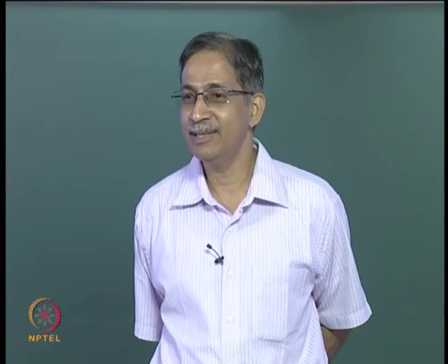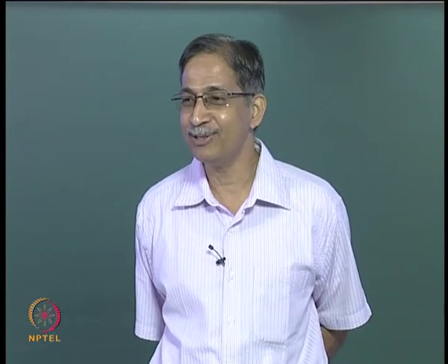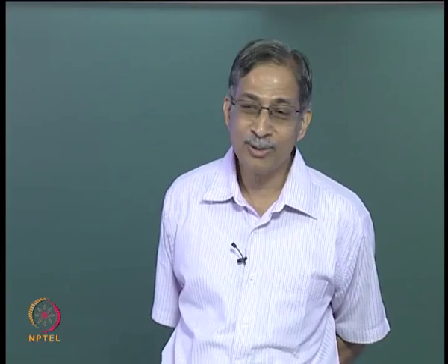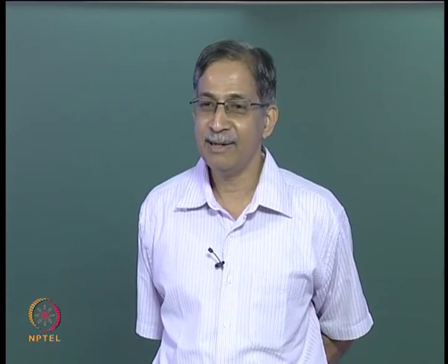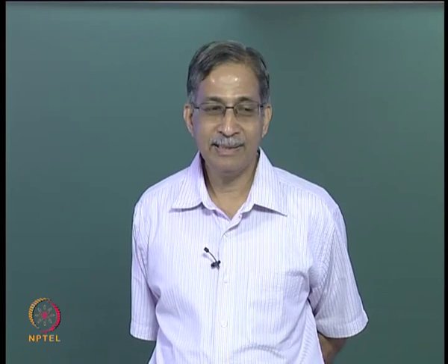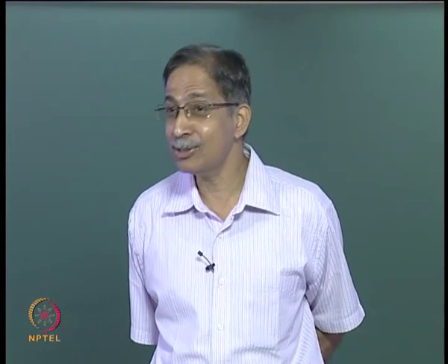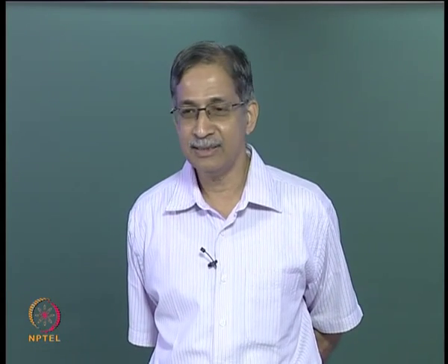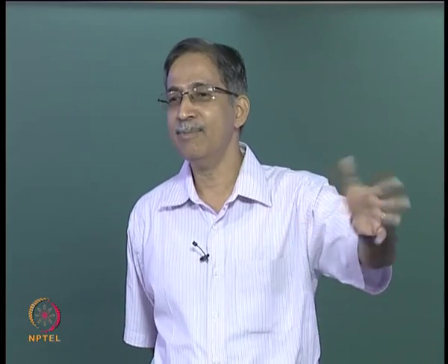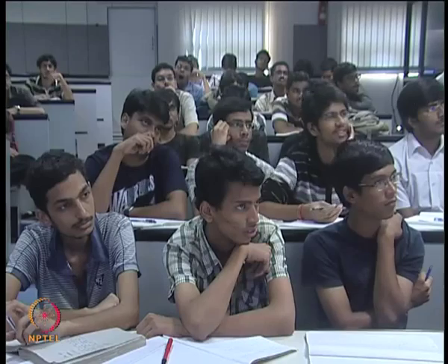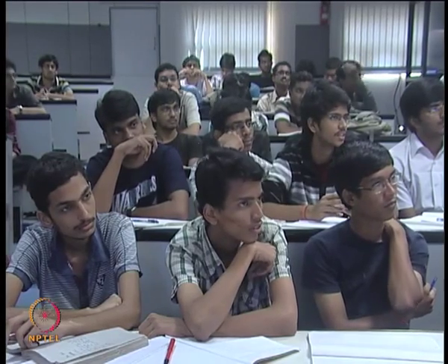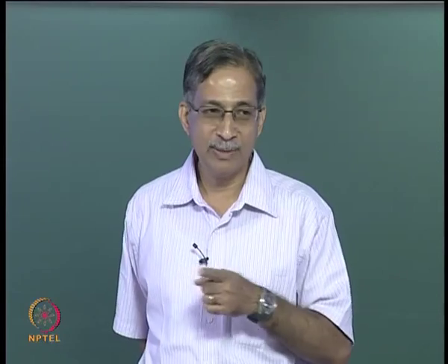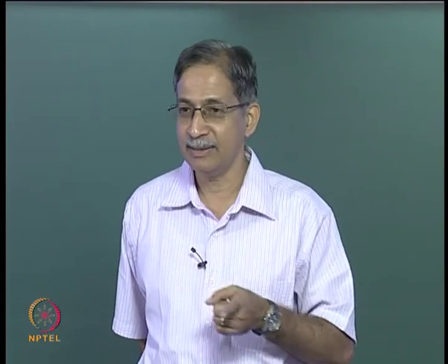Really beautiful. Just 0.9 kilonewton is the force that you get, not 20 kilonewton, not 40 kilonewton, not 100 kilonewton, not 990 kilonewton. So at the end of the day, you'll find that thanks to this analysis, you can confidently say, I don't need to worry about temperature changes for a frame like this. But you wouldn't be able to say it with that degree of confidence unless you could analyze the structure and interpret the results. Is it clear?